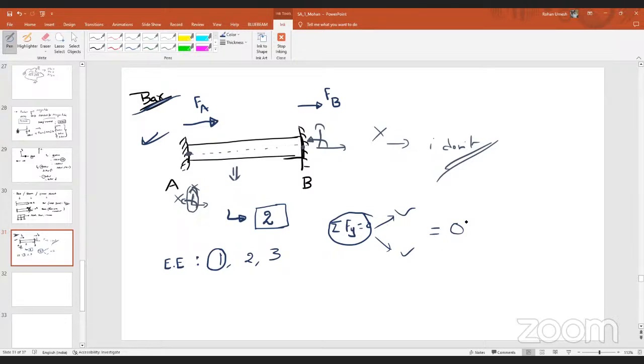Then how can you make them equal to 0? You can't, right? So in whichever direction the forces are acting, you have to make the sum of forces along that direction equal to 0. In this case, there are no forces acting along the y direction and no moment. So even if you don't consider summation of F equal to 0 or summation of moment equal to 0, they will be automatically satisfied, or we can say that they don't exist.